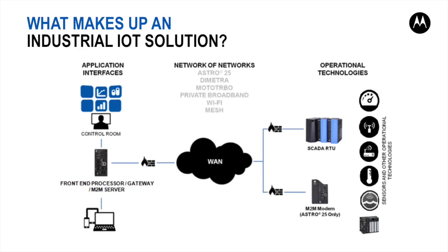First, let us clarify the terminology used when dealing with industrial IoT, aka SCADA and M2M. SCADA, which stands for Supervisory Control and Data Acquisition, refers to a real-time process control system used to centrally monitor and control remote or local equipment such as motors, valves, pumps, relays, sensors, etc. SCADA is a combination of telemetry and data acquisition.